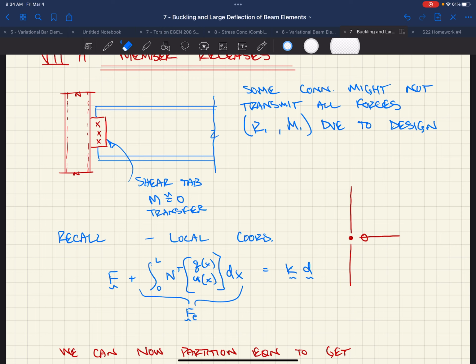And the code allows you to do rigid diaphragms, right? If your displacement of the diaphragm is less than the overall displacement, or vice versa, then you would have this assumed flexible behavior of your diaphragm, so that it's way more stiff than or way more flexible than your lateral system is. So you could just say, well, hey, the code tells me I can take this little shortcut, right? Or you can nerd out and just design it and put it in RAM and have it do it. Can you do wood diaphragms in RAM? I assume you can, right?